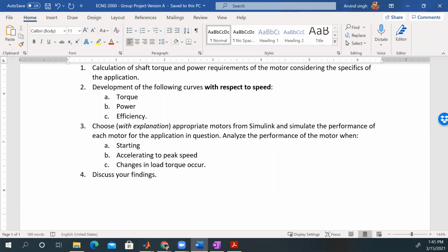So if somebody says a 12mm shaft, which is in metric units, the equivalent people will say is a ½ inch. ½ inch is really 12.5mm. So what do you think is going to happen when you try to fit the shaft in the wheel? It's just a hair too big, right? These are the sort of practical issues you come up with,